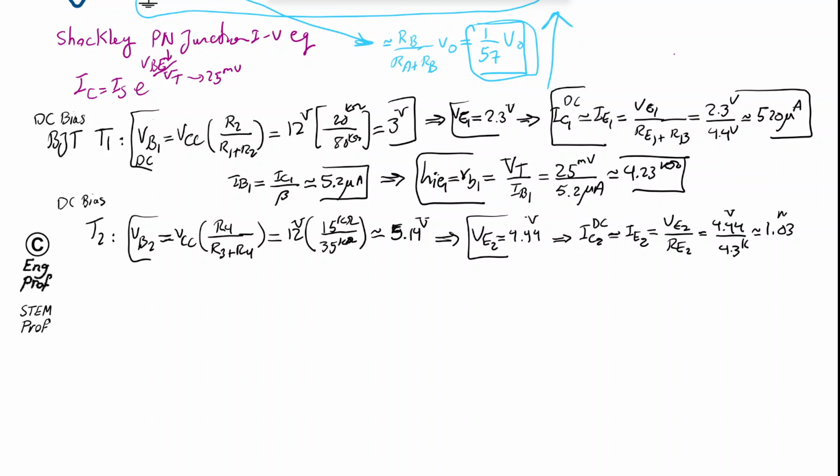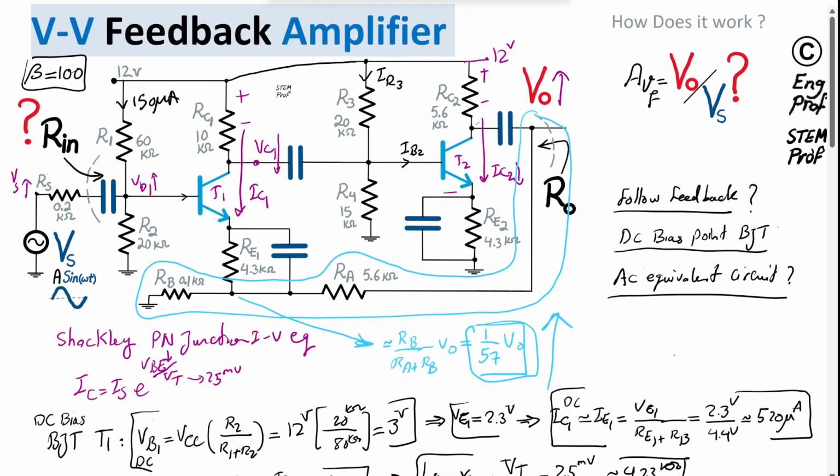So the DC current of the base of transistor 2, which is the collector current divided by beta of the transistor, turns out to be on the order of 10 microamp, which is again small. So the assumption we made, that we just considered these two resistors in series neglecting the impact of IB2, is a valid one, because this current is much larger than the IB2 DC-wise.